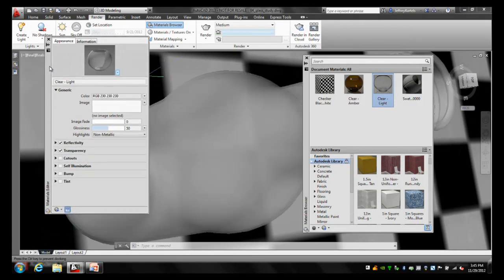And in the materials editor, you can see that the first time we brought this up, we dealt with the wall paint, and we dealt with that flooring. This one obviously has many more settings. Okay? Some materials are based on real-world templates like ceramic and glass, wood, things like that. This material was based on a generic template, so it gives you access to all of the properties. If you look in here, you can see that the properties are categorized in these collapsible sections.